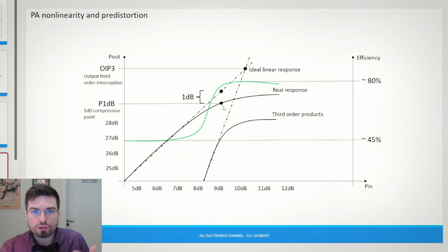So as we approach saturation, we can create amplifier topologies like class B, class C, class E, class F. We can create different topologies where the active device behaves much more like a switch, working much more in the on and off states, with more tricks to phase align the current and voltage waveforms to reduce the power dissipated in the active device. And all the efficiency gains we have with these different topologies and tricks will make the operation much nearer to the 1 dB compression point, when the amplifier will start to distort but will deliver higher efficiency.